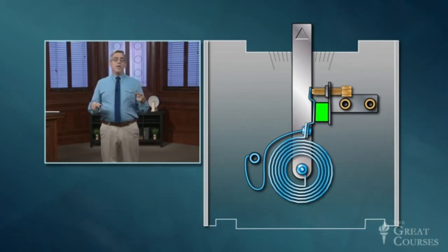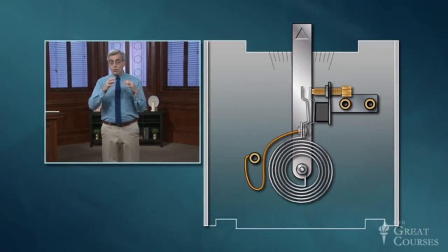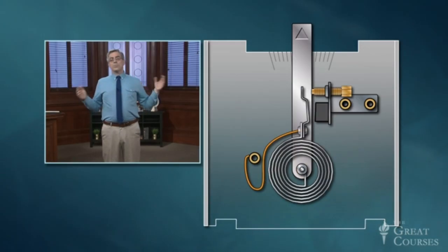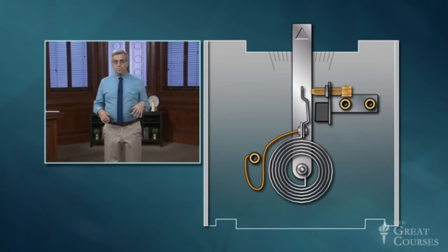to switch on. Now, as the temperature in the room begins to rise, the coil tries to unwind, but initially it's prevented from doing so by the magnet. Eventually, as the temperature continues to increase, the bending force in the coil gets strong enough to overcome the magnet, and the contacts pull apart. The circuit is now broken, the heat shuts off, and the cycle starts anew.